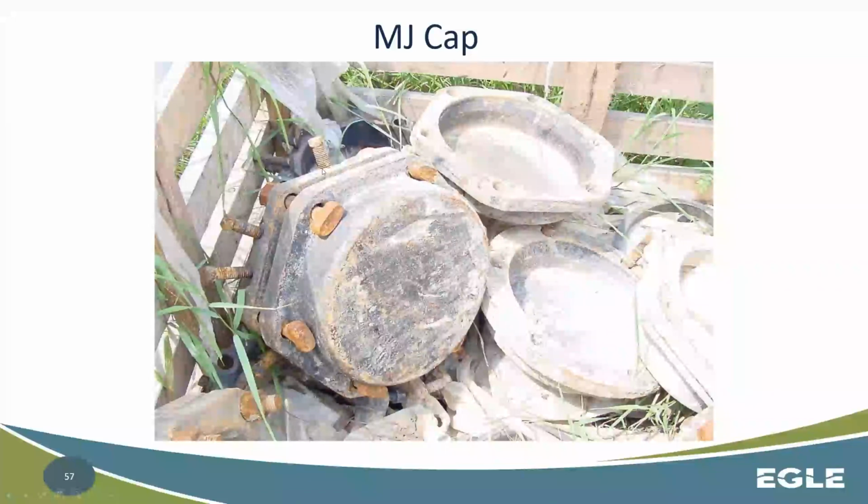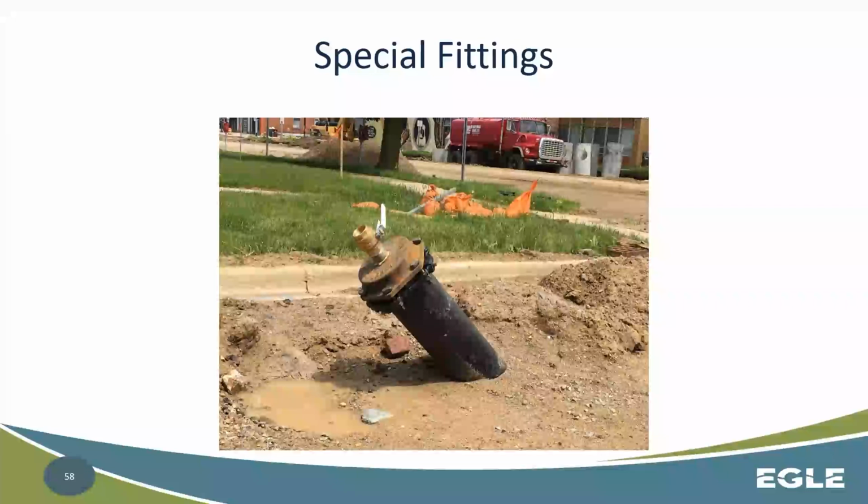So you've got these screws going down that are actually going to bite into the pipe wall itself, not just the cap sitting at the end, which could easily blow off if there's excessive water hammer or something like that.